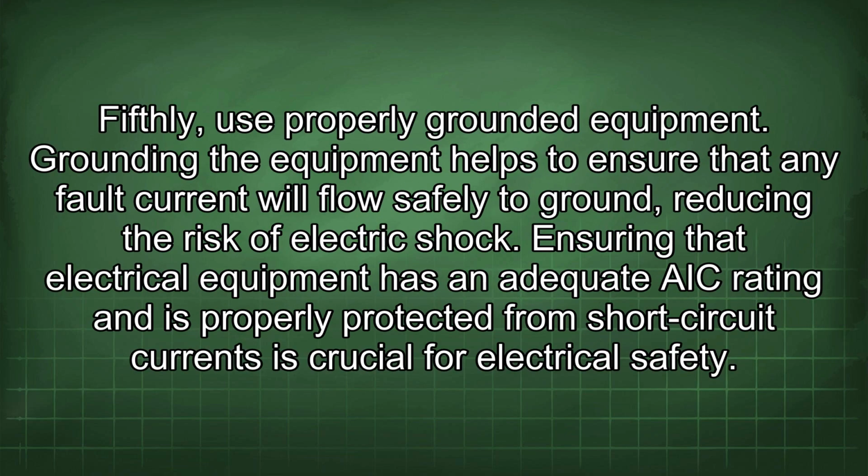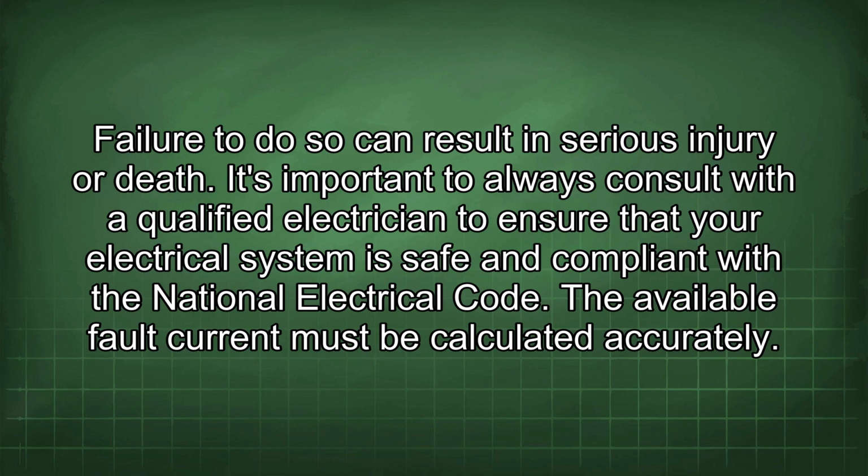Fifthly, use properly grounded equipment. Grounding the equipment helps to ensure that any fault current will flow safely to ground, reducing the risk of electric shock. Ensuring that electrical equipment has an adequate AIC rating and is properly protected from short-circuit currents is crucial for electrical safety. Failure to do so can result in serious injury or death.